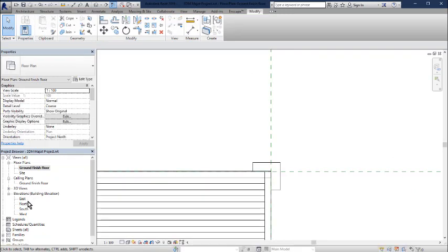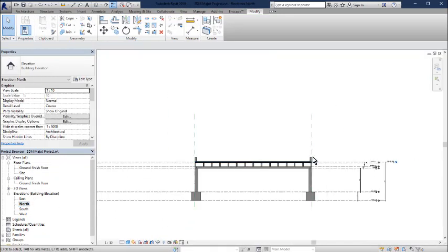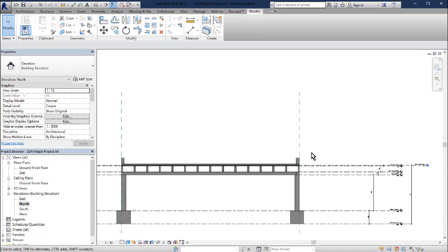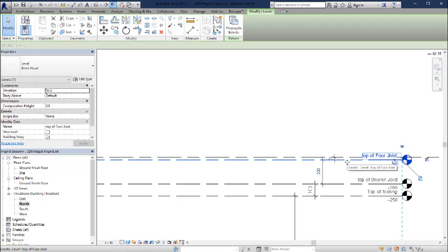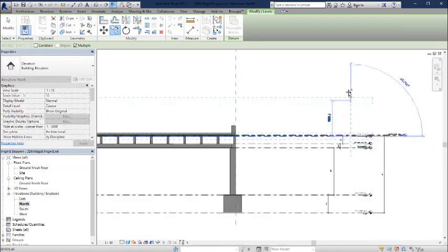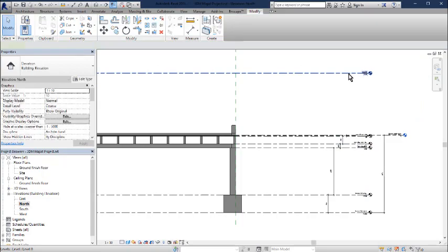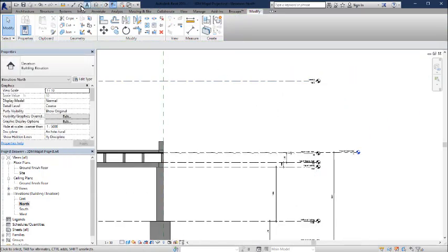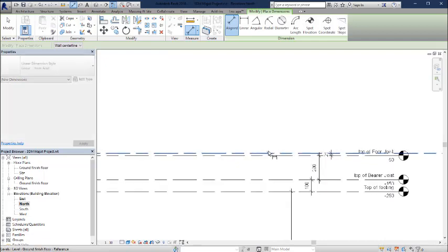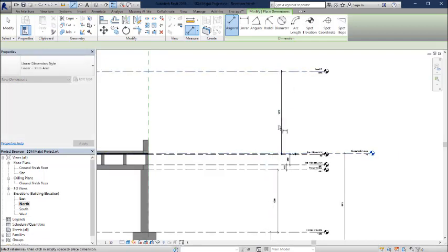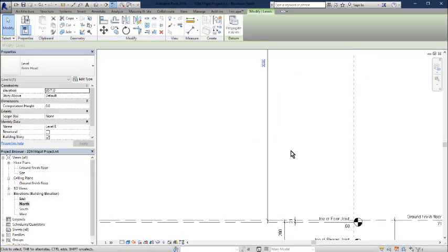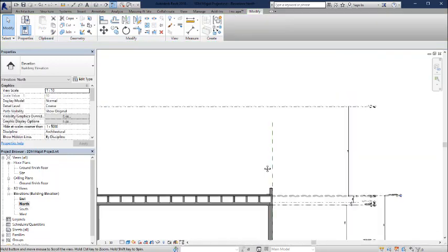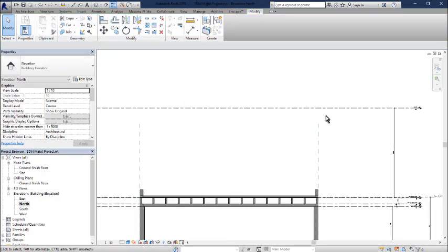Let's choose OK for now. And if we look back on our view here, we need to set how tall our floor level is going to be. So mine is going to be 10 feet. So I'm going to copy a level up, and this level here, it's another empty level. I'm going to use my dimension lines and go from the ground floor to here. And I'm going to make this 10 feet, about 3,000 millimeters.